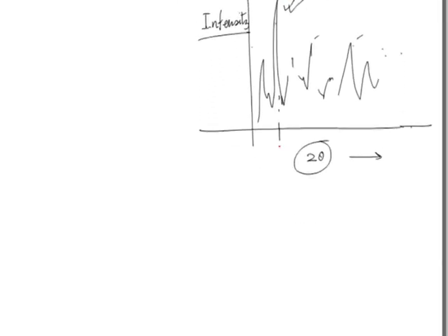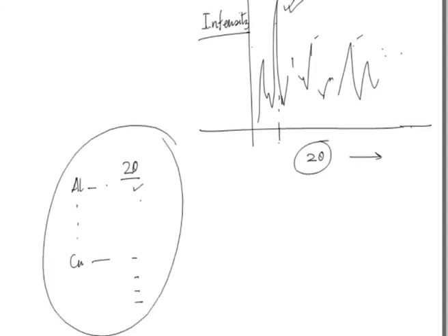because this 2 theta for different materials, say aluminum for different phases, is fixed. Similarly, for copper different phases, this value is fixed. Now, by correlating these values, if we obtain these values here, then by identifying the peak corresponding to that particular 2 theta value, one can identify the element present in that material.